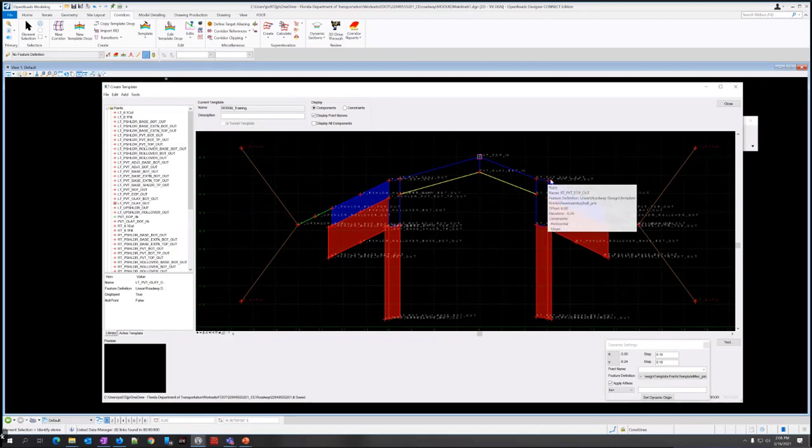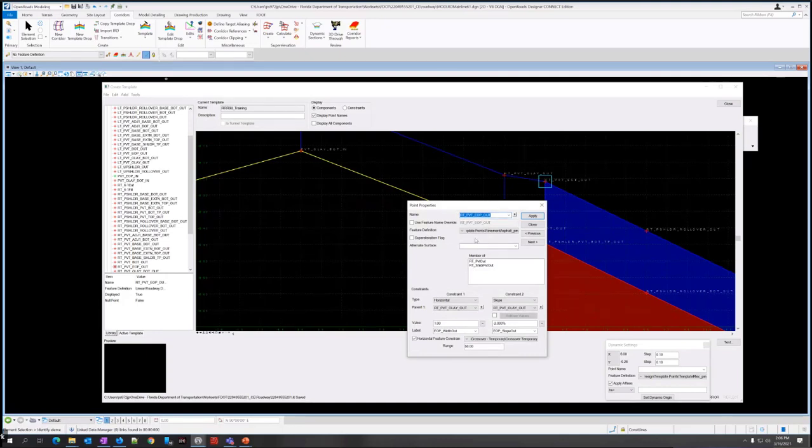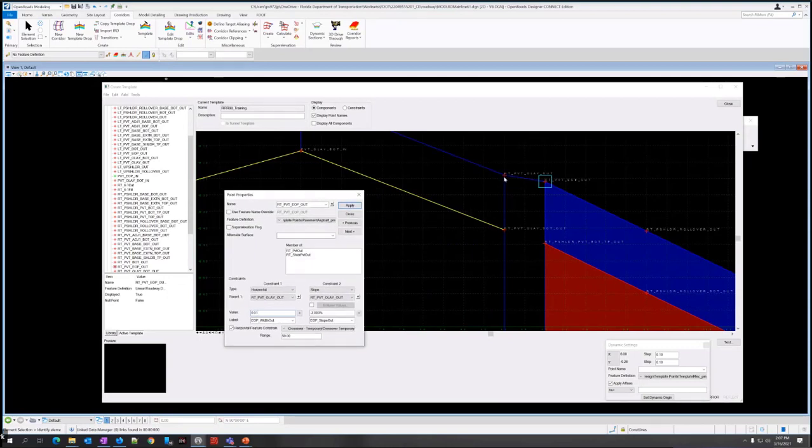All right, so now we need to do the right pavement EOP out. That's this point over here. I'm going to double click to edit that. Horizontal, I'm going to change it to 0.01. Now essentially what we're trying to do here is basically the widening can go from 0 to nothing, but if you do 0, it'll stack the point on top of it.